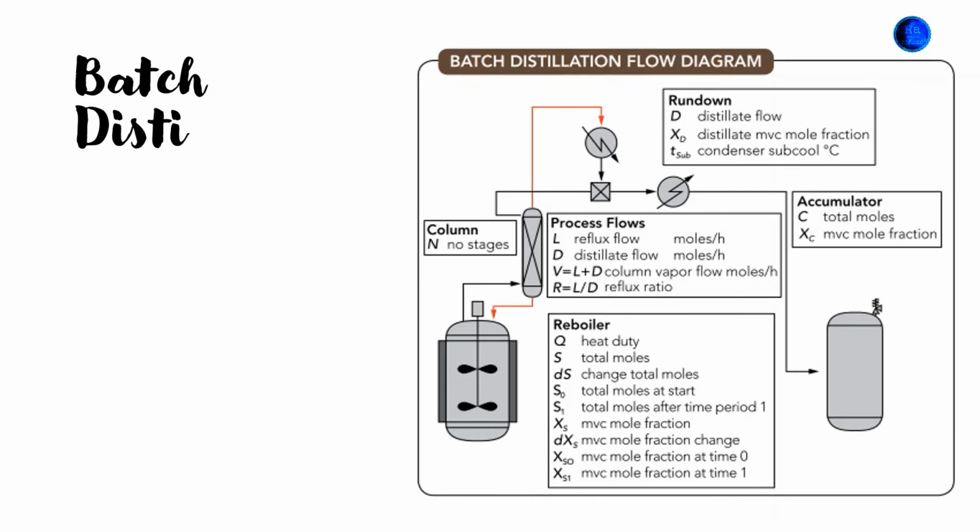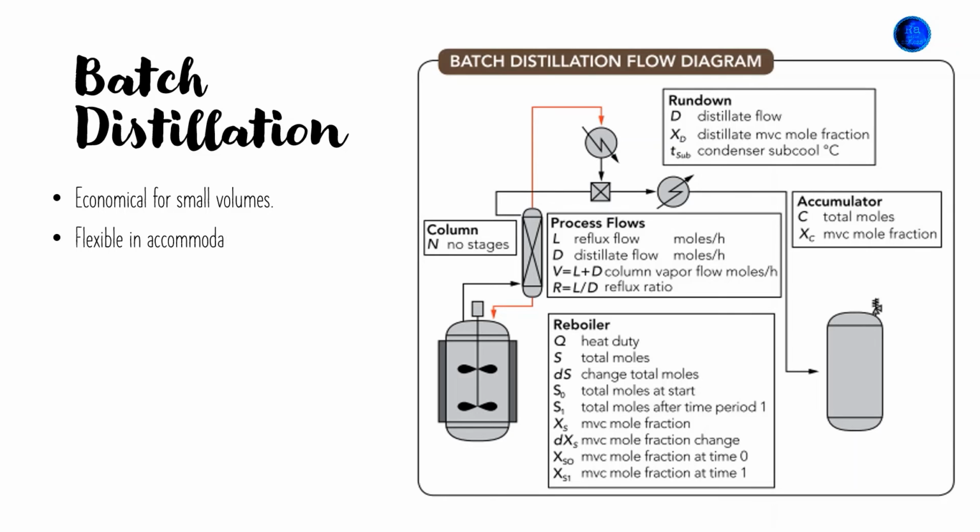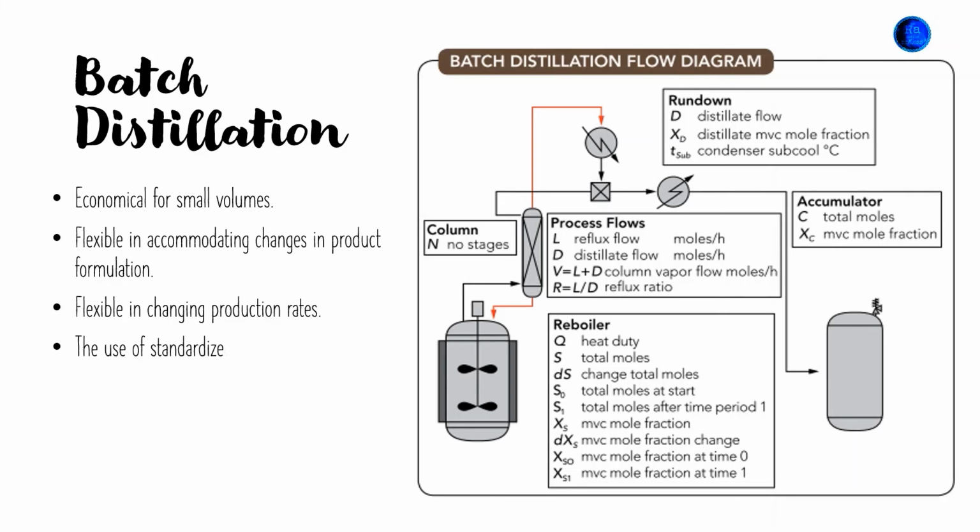Batch distillation is used extensively in small-scale production units where the same piece of equipment is used for many different mixtures and where small quantities of the liquid mixture are to be handled. It is useful when more than one product is to be obtained and when the liquid mixture to be separated is high in solid content, for example tar.